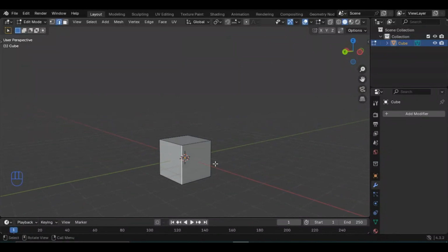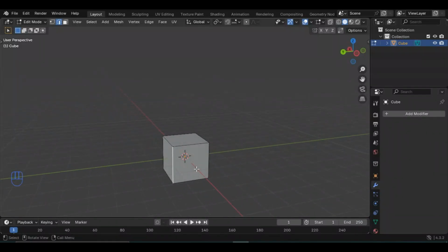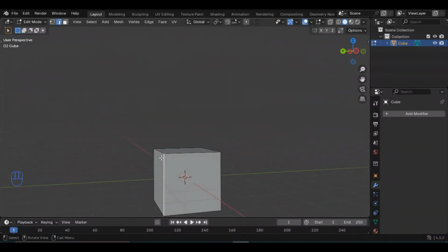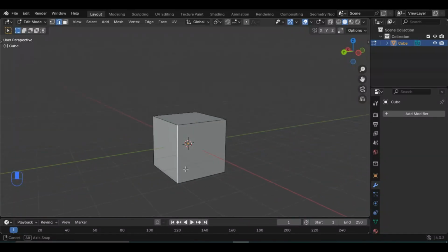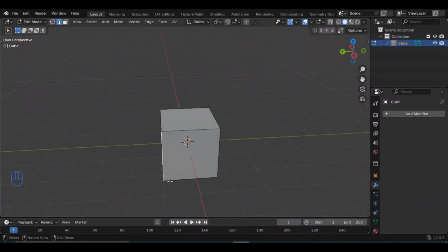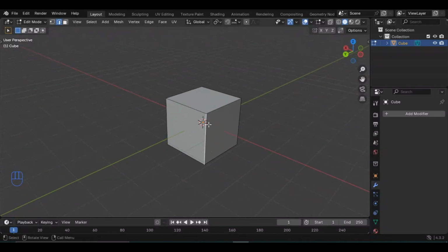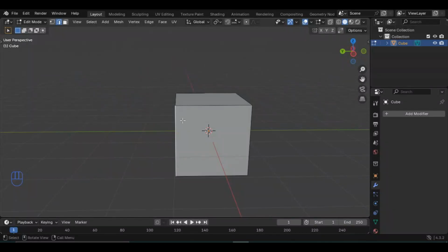The bevel in Blender is a very powerful tool. In 2D, you could call it something like a fillet, but here it's a bevel, and it can actually turn these straight edges into curved edges, and that's what we want to accomplish. This is very applicable when you are working in architectural design, in 3D design, and you want to design your pillars or your walls, because in reality the edges of walls are not usually this straight.